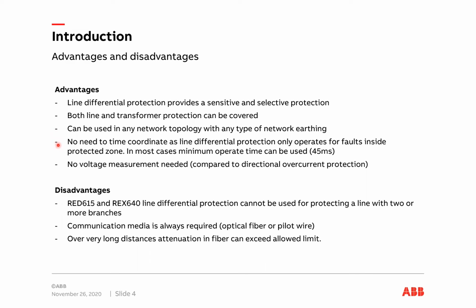And there's no need to do any time coordination like for overcurrent protection, since we are only looking at the differential current.